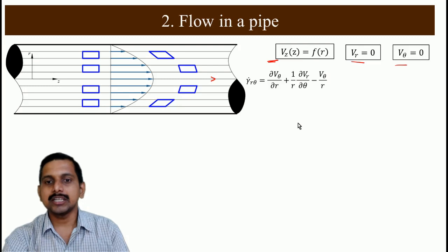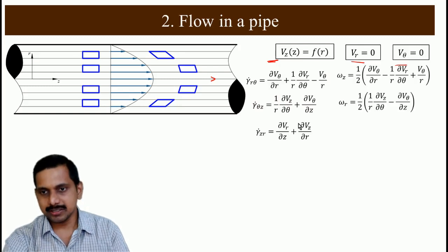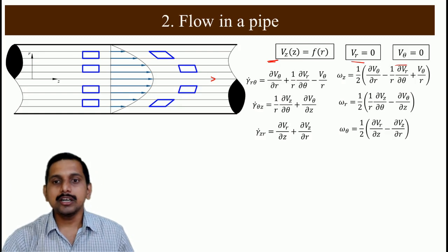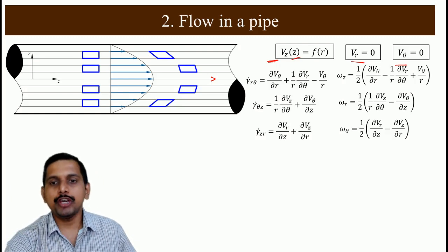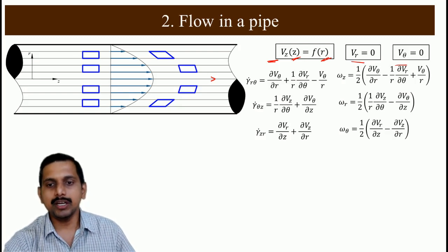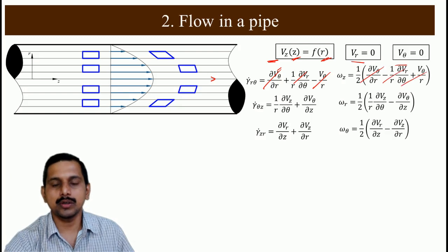We will take the cylindrical coordinate systems, and here what is important is the Vz. Now Vz as a function of r has only some value. Other than that, everything goes to 0. That means wherever Vz is differentiated with r, only those components remain. So here there is no Vz, V theta, this is 0, this is gone. So that's why this whole thing goes to 0.